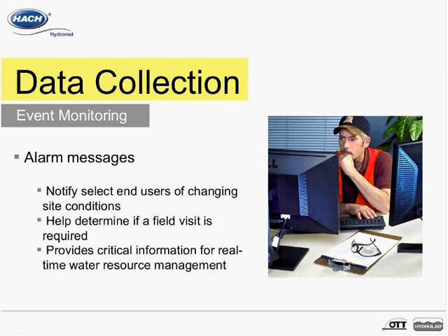For example, if the conductivity value increases in a groundwater well and the water level decreases, there could be a potential issue where saline water is infiltrating into the aquifer. To prevent this intrusion, the monitoring agency may initiate artificial recharge using injection wells to create a barrier against saltwater intrusion.